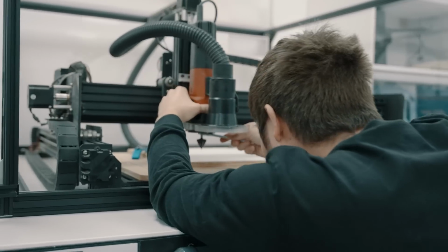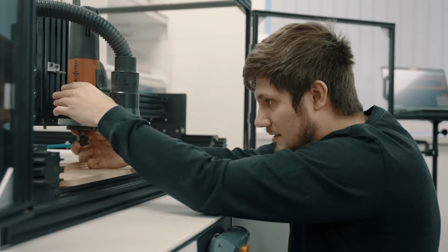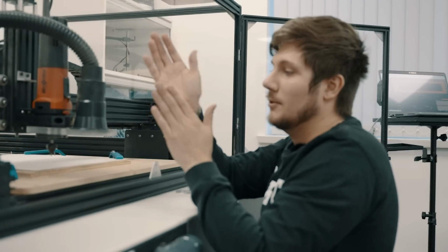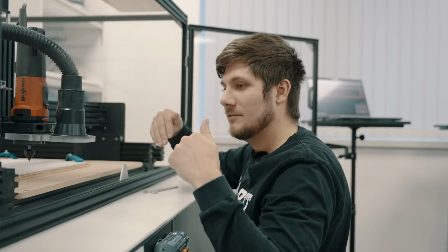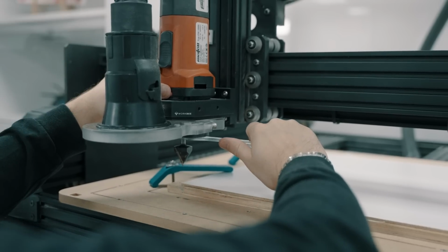So I'm using a V-bit so I can get into all the corners, because with an end mill obviously it's a much wider head of the tool, whereas with a V-bit it's to a point, so I can get in all the corners. Also the bevel or chamfer, when I'm spraying it, should help direct the paint as well. So we've got this all in the machine, we've got the 3 bits of material there. All that's left to do is run the toolpaths. They should be pretty straightforward and pretty quick. So yeah, let's go.